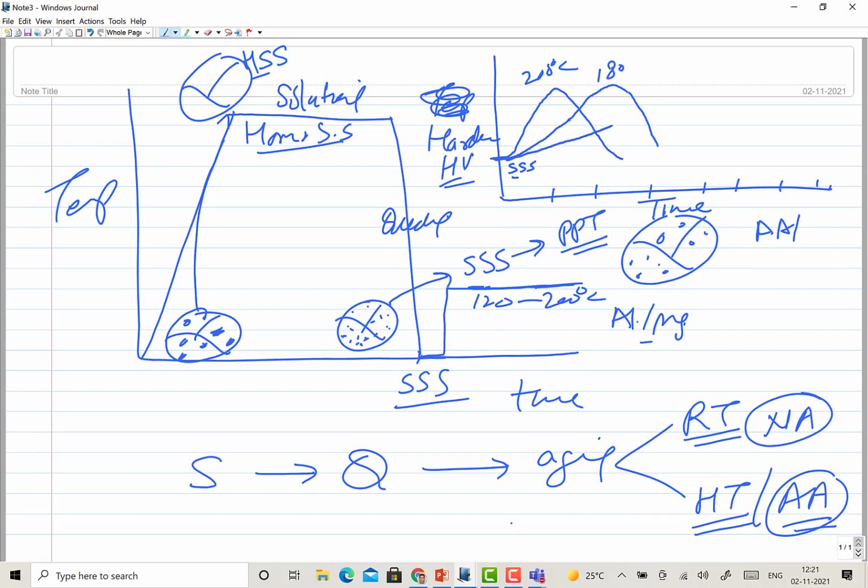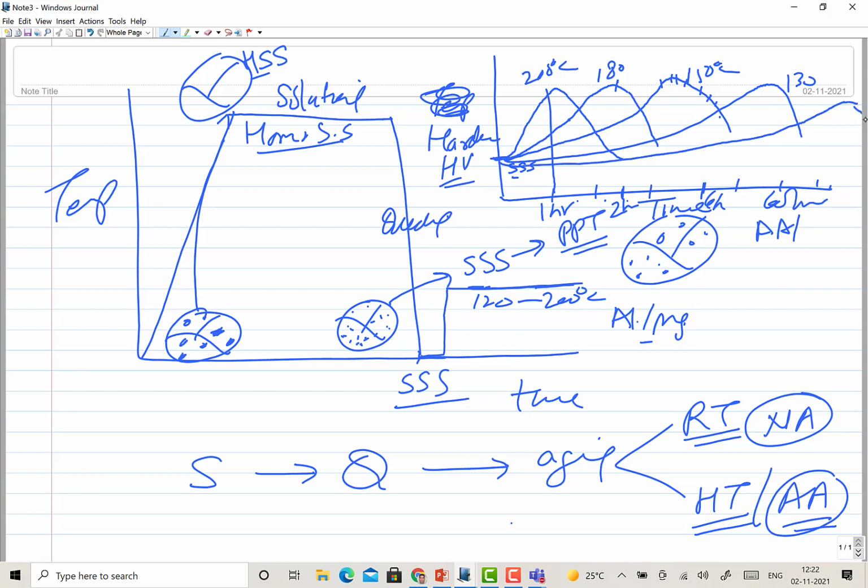So further, when you use a lower temperature of exposure, say 150 degrees centigrade, it takes further longer time to reach the peak hardness and then it starts decreasing like this. Okay, so this is say 130, and this may be just 1 hour. This may be 180, peak hardness being achieved say after 2 hours. Here it may take 6 hours, and here it may take even 60 hours. So a very long time it may take when very low temperature is used, and at room temperature, it may take like 10 to 15 days when it is done at 24 degrees centigrade.